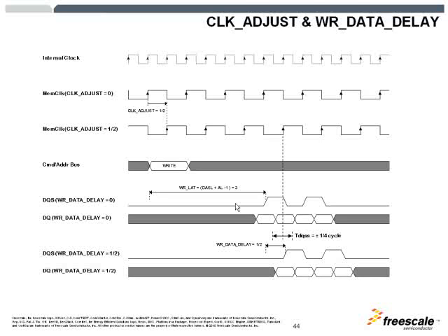As we discussed earlier, SDRAMs are very simple devices, and we need to provide the clock and the address and commands in a fashion where, as soon as they see the rising edge of the clock, they will sample the information on the address and command lines.